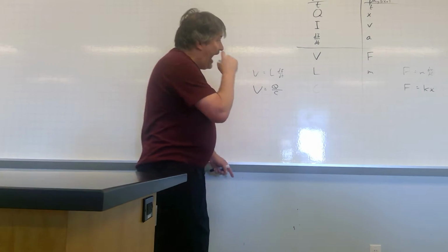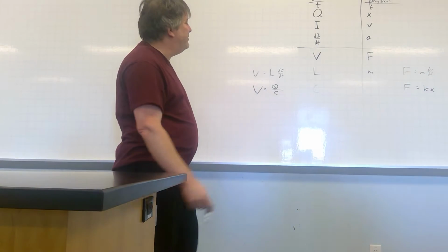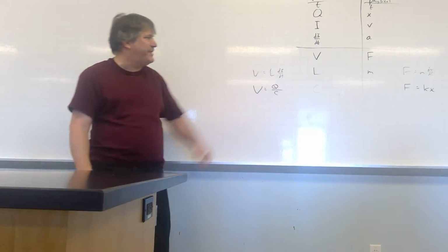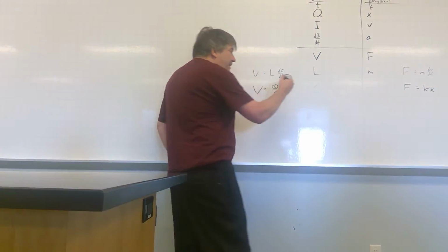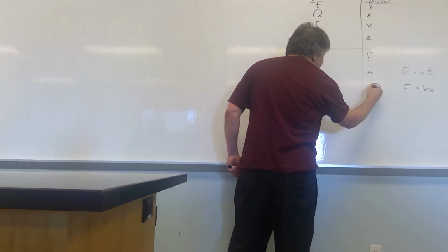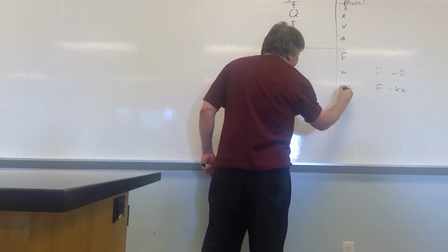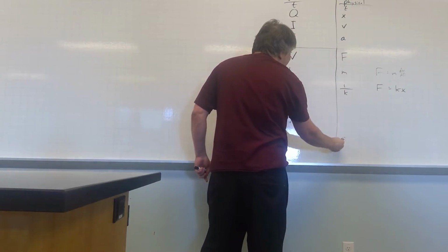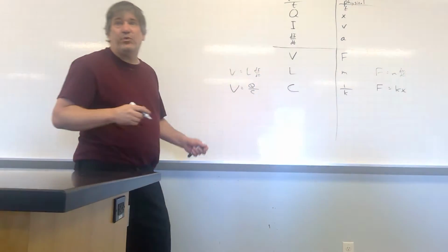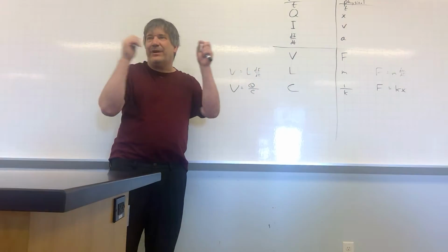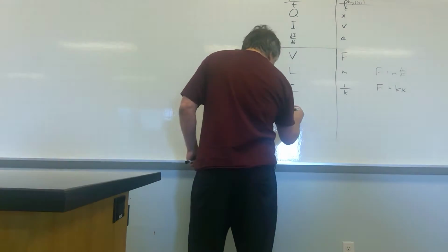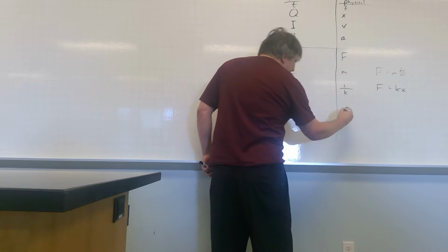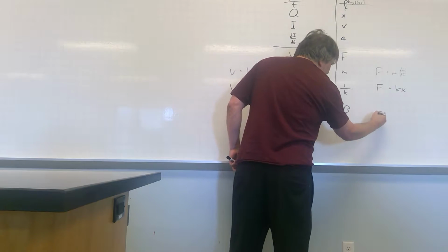Except that our spring constant we usually put in the numerator of that equation. Our capacitance went in the denominator, so that means actually the capacitance C is analogous to 1 over the spring constant. A high capacitance means a very weak spring. A low capacitance means a very stiff spring, high spring constant. And finally, resistance is analogous to viscous friction.